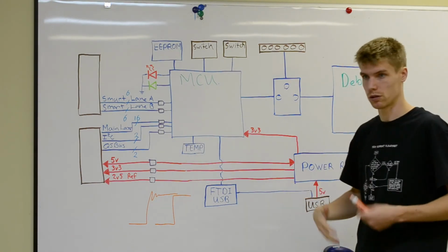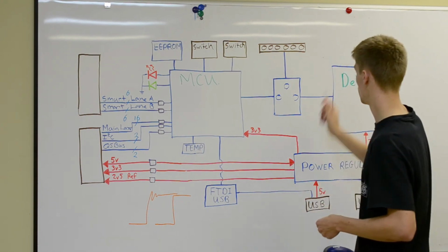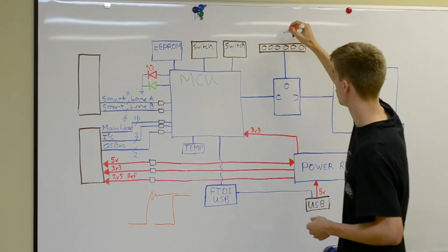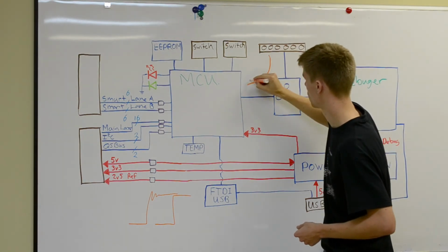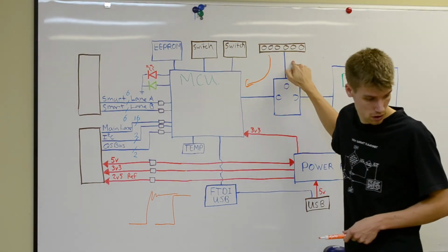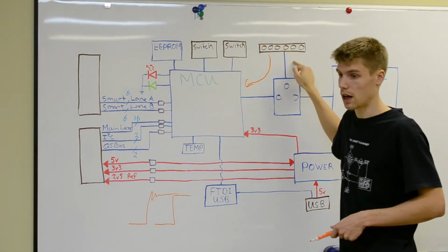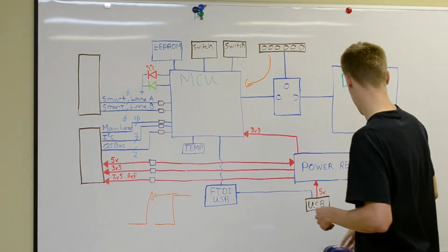It's way more powerful than doing printf statements or something like that. So the other way you can use it is to connect that debugger to the external link, and then you can program this way. There's a small solder jumper on the back of the Hello, which is used to set that.